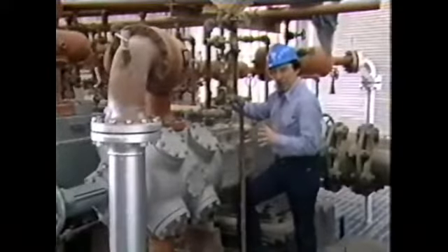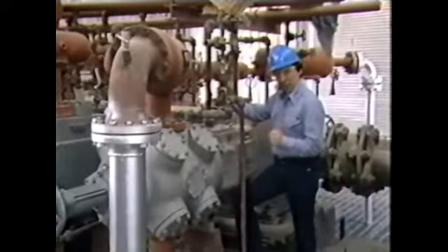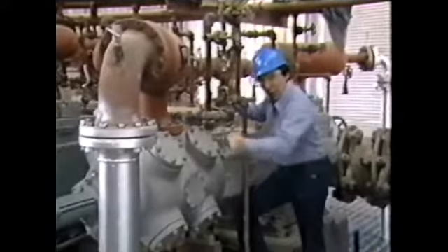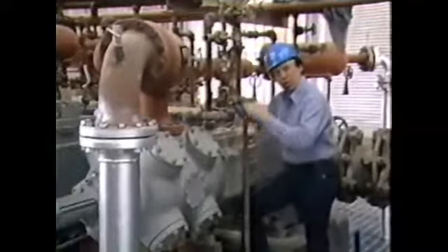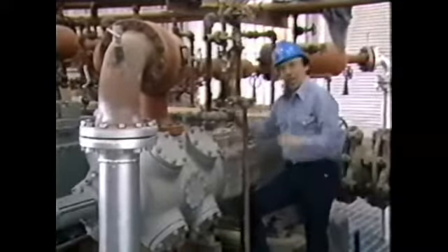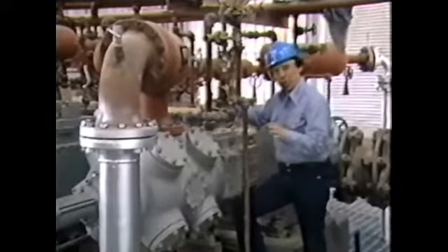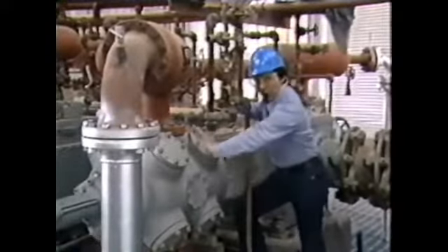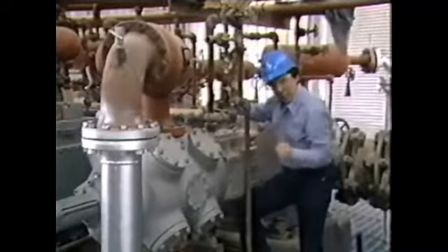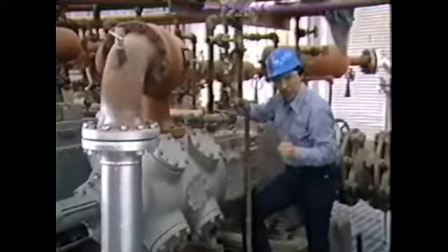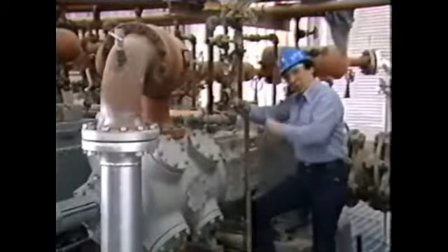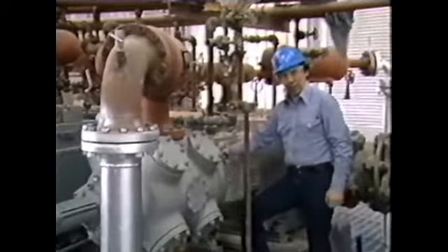Now, the double-acting compressor compresses gas during both the forward and back strokes. On the forward stroke, gas is drawn into the cylinder through the suction valve on the drive end. At the same time, gas is being compressed and discharged away from the drive end on the opposite side of the piston. On the back stroke, the process is reversed. Gas is drawn into the cylinder away from the drive, and gas is discharged on the drive end.